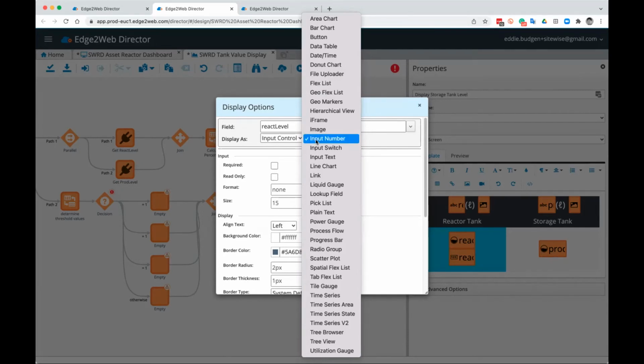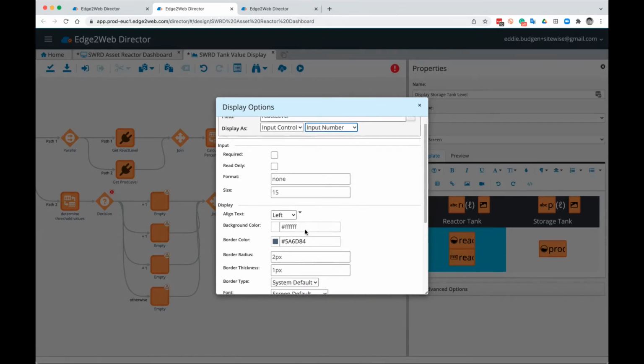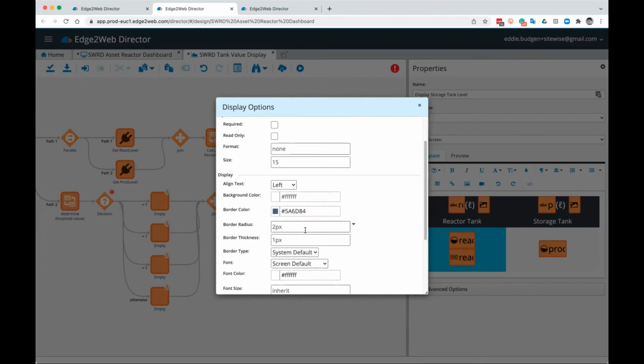For this screen, we chose a text renderer for the table header fields, and within the table, liquid gauges to represent the levels of the specific tanks. Each data renderer has numerous display options. These can be overridden specifically for this particular case, or data-driven at runtime if a more dynamic presentation style is required. Default values are set on the page using a theme, which is a configurable collection of all display options that you can adjust and create custom themes for branding or specific presentation needs.